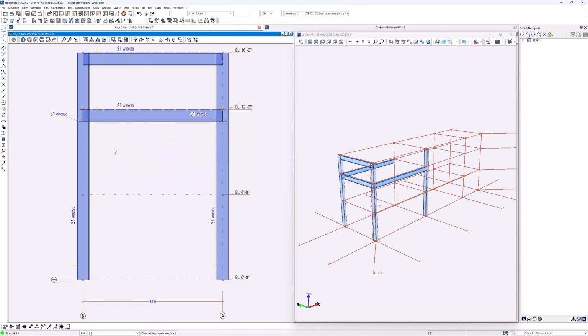It can be very useful for purlins sometimes, especially in a sloped case, since now I'm picking one point and pressing enter to confirm, but if I press 1, 2, as we can see, that component will now be tilted according to the second point we pick. But if we say no, it just has to be horizontal, then 1 point is enough, followed by an enter.